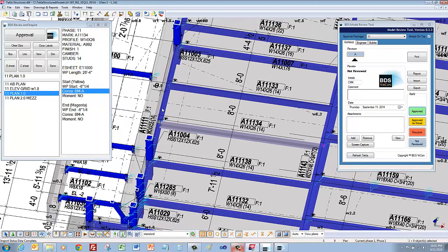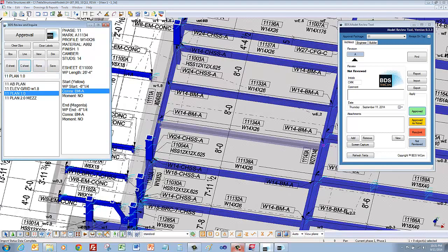This is currently showing the erection drawing here within the model, but if we'd like to see the connection map drawing, we can go ahead and press the C sheet button. This then loads the connection map drawing and shows the corresponding connection codes towards the end of that particular member. So with that way we can either visually check it here and compare it to the connection map design drawings, or we can just look at the connection code here in the properties list.